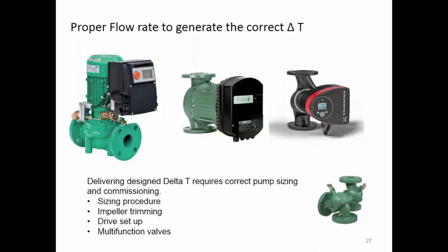It's about velocity, it's about flow right through the heat emitters and how much heat is coming off. So when we start to look at how we size pumps plays a big factor into what kind of delta T. And when I say what kind of delta T, now I'm talking about actual realized delta T, not theoretical. This is the delta T that we're going to design around.